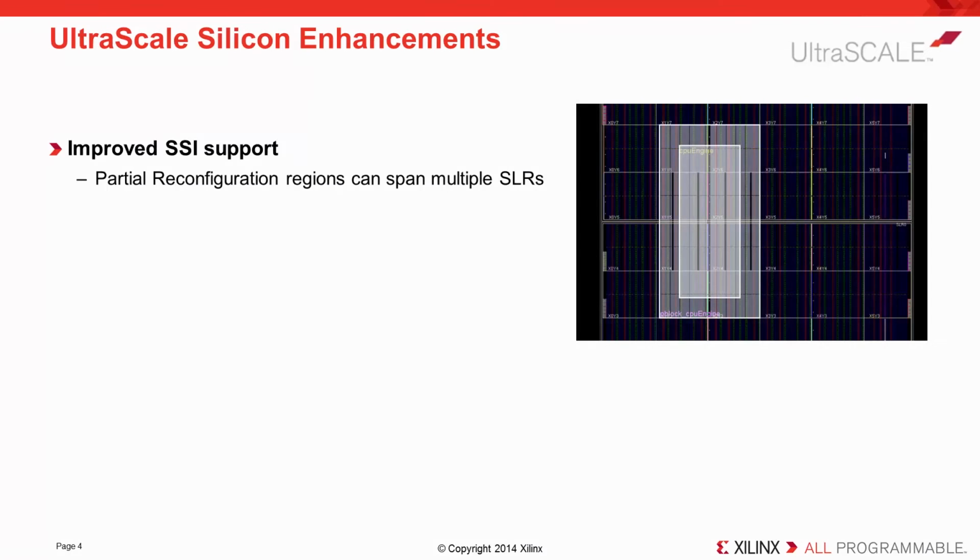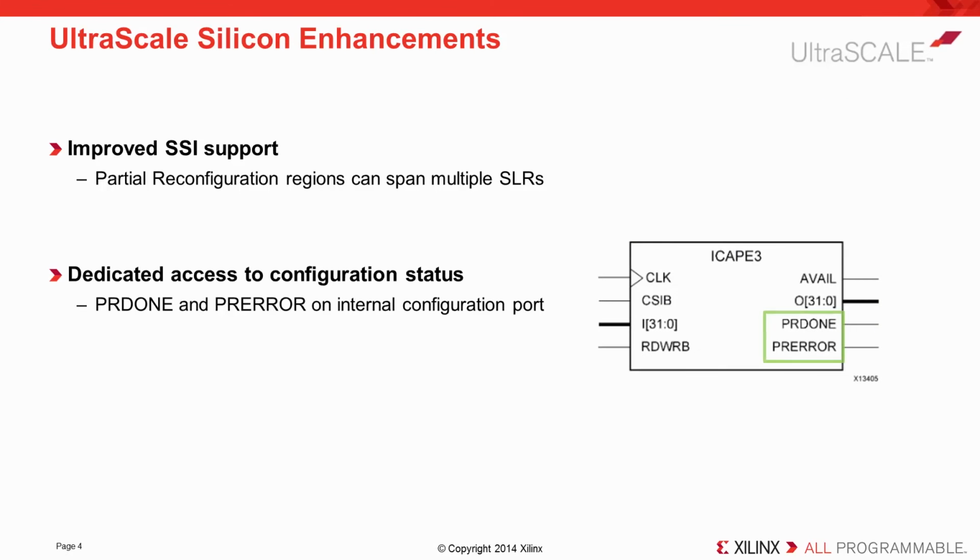UltraScale offers improved support for devices utilizing SSI technology. The new Laguna interfaces that connect superlogic regions can be included in reconfigurable partitions, which means these regions can be as tall as necessary, even spanning multiple SLRs. The ICAP now has dedicated ports that echo the behavior of the external pins DONE and INIT_B. PR done and PR error are pins on the ICAP primitive that can be monitored by your design logic or Vivado debug circuitry to confirm that partial reconfiguration has been successful.